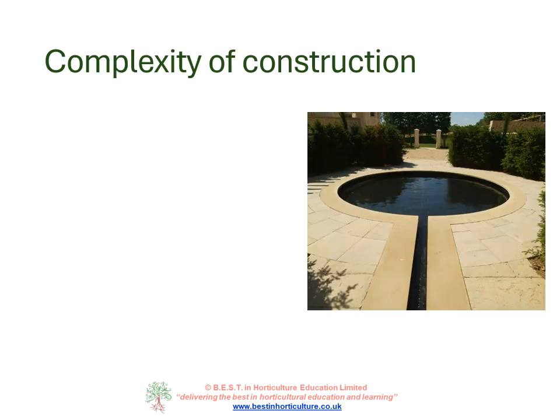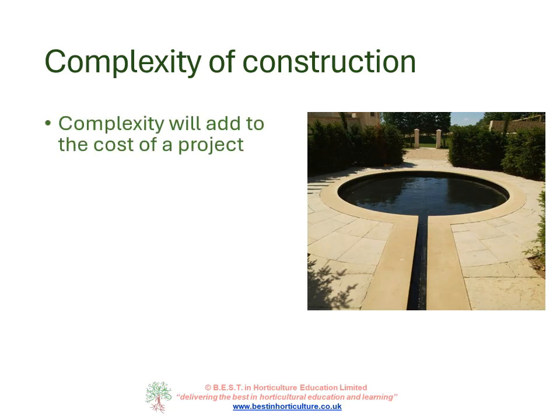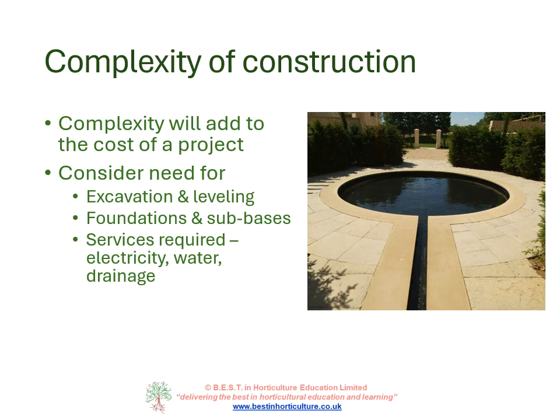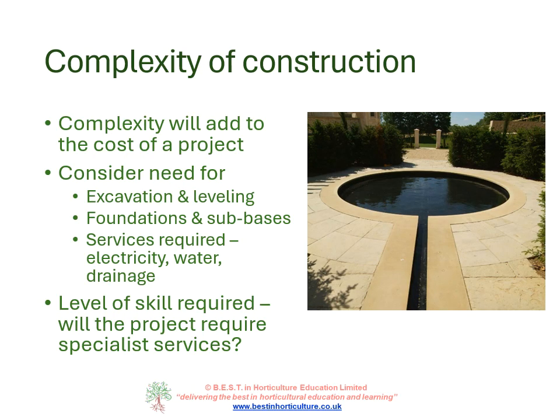Thinking next about the complexity of construction. Complexity will obviously add to the cost of a project. So when planning, consider the need for excavation and levelling, foundations and subbases, any services that might be required, electricity, water, drainage, and also the level of skill required. Will the project require specialist services?